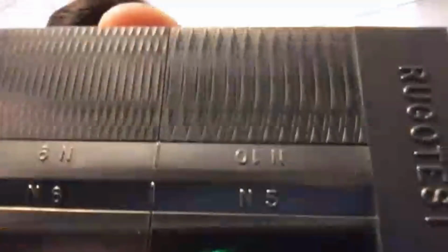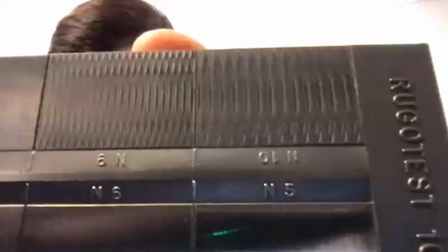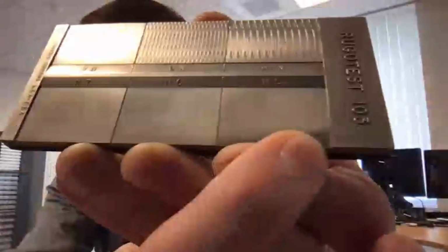And you can see that this is a fingerprint of the face milling process in different scales, and it goes from a very rough one like here, to smoother, ending up with almost, yet again, a mirror-like smoothness. So you can see how the reflection changes from sample to sample.